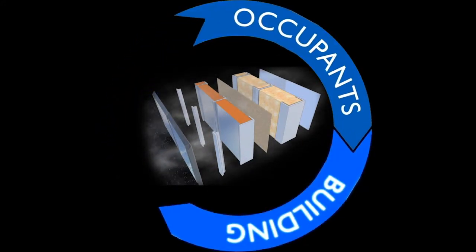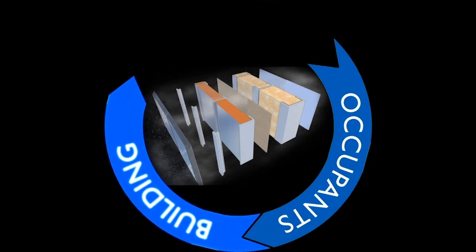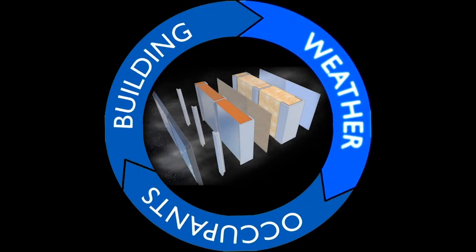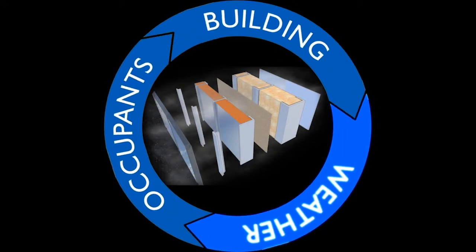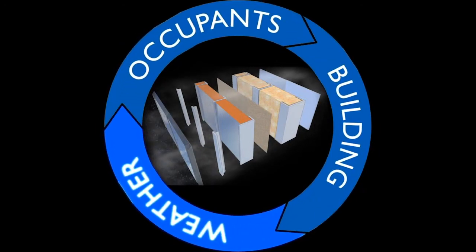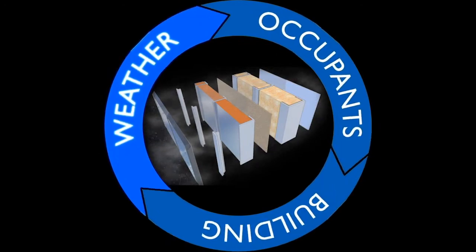They should then consider the physical properties of the construction, separating inside from outside, and how this interacts with the various moisture sources present. Lastly, designers should consider the effects of the external climate, which, being site-related, is beyond direct control, but may be moderated by the building's form and orientation in relation to topography, prevailing winds, sunlight, and overshadowing.